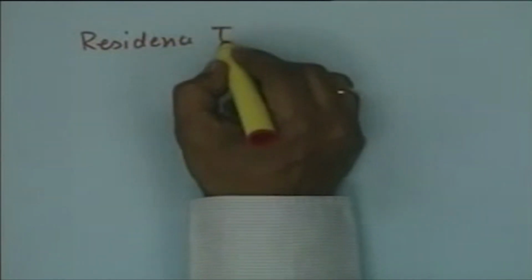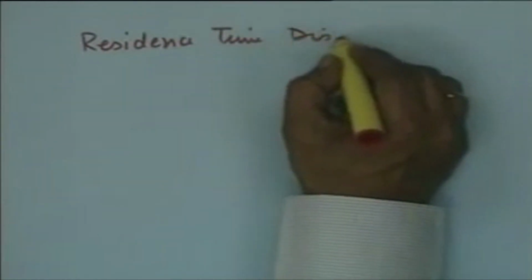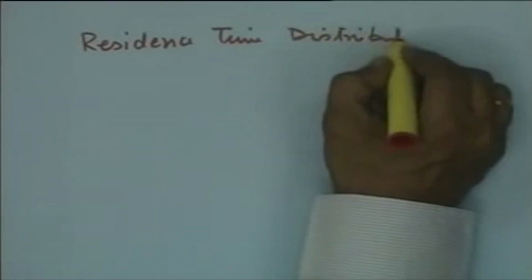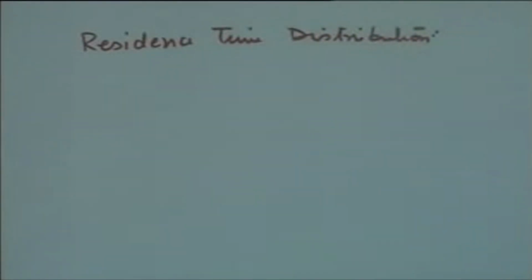Now, this analysis to monitor the deviation from ideality in flow pattern for an enzyme reactor is mediated by what we call residence time distribution. Essentially it gives you the distribution of the various elements of the fluid passing through a reactor, that is, the age of various elements in a fluid stream from the reactor, in terms of age distribution.